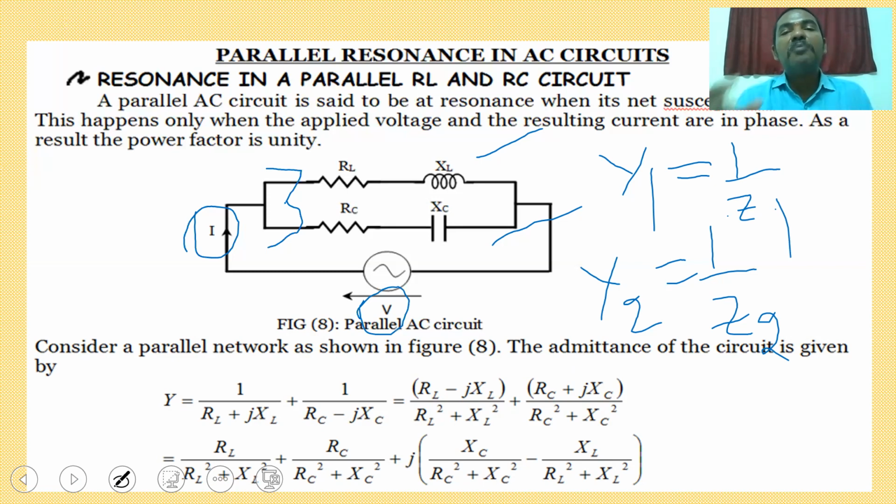The net imaginary part, or net susceptance value, is equal to 0. The total admittance must be equal to your total conductance value, so the power factor must be unity. The voltage drop across one branch and across the second branch is also the same. The current values are divided because the two branches are connected in parallel with respect to the net current.